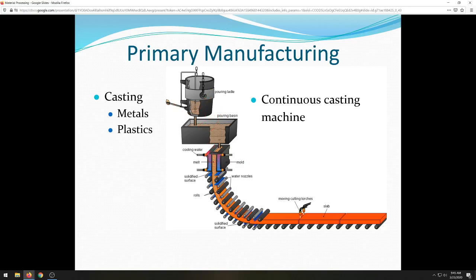It goes down through this specialized tool here called the mold, that actually is basically lined with water, and it attempts to cool and solidify the material as rapidly as it can, so that it can then be solidified by the time it gets to just to the mouth of the part here, and then it gets down here and it's formed by rollers into some sort of standardized slab, and then in the case of steel at least, cutting